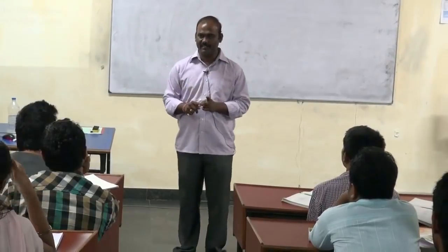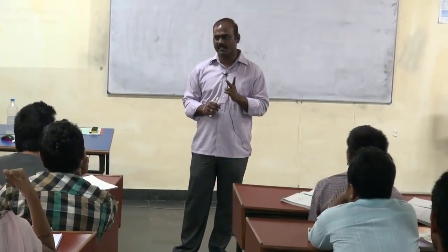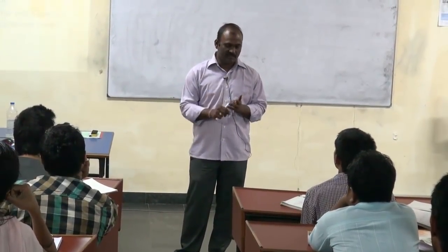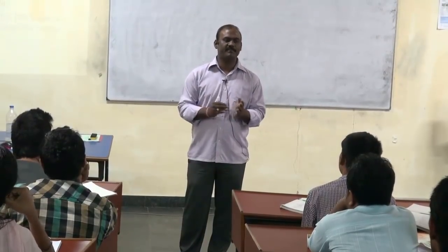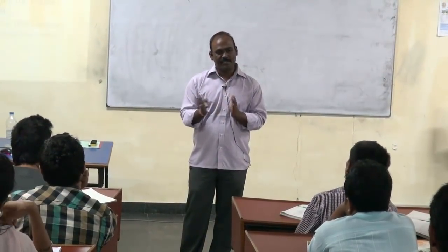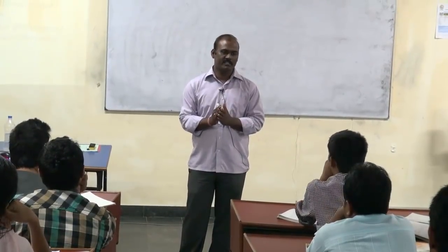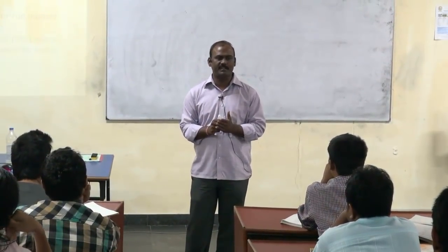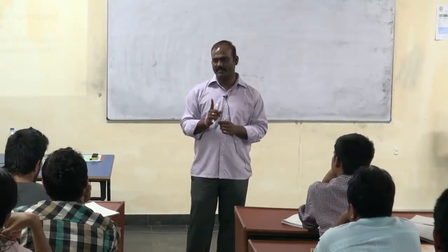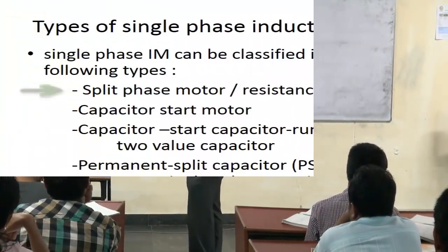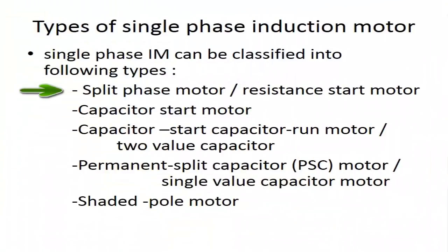Though it is a single phase induction motor, two phases are available at the beginning of starting, but one phase will be cut off after starting. After starting, one phase will be cut off and the motor will run with the help of only one phase, right? So the first one is the phase split motor, or resistance start motor.